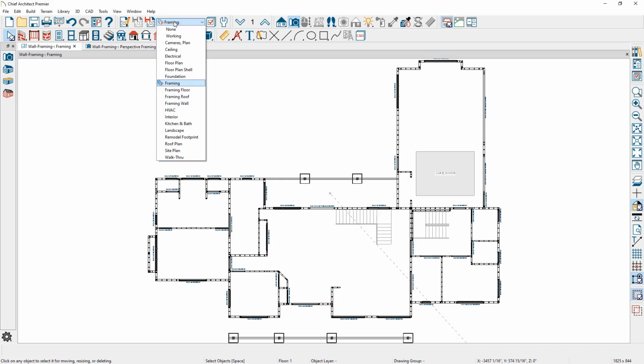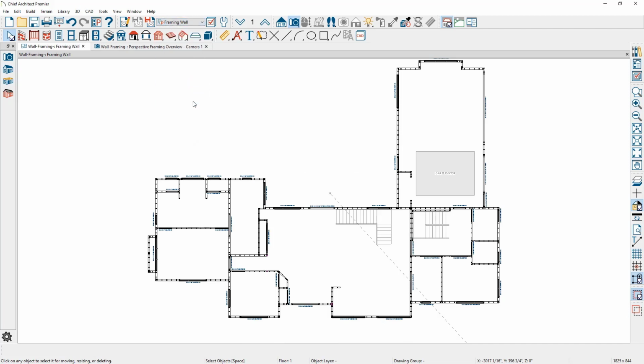This can get a little bit cluttered when you have floor framing and roof framing on. I like to build a defined Save Plan view specifically for wall framing and a corresponding layer set. You can see I've actually already created a Save Plan view for the wall framing. It doesn't do a lot, but if I'm using that, it will turn off the framing for the roof and the floor should that be created in your project.